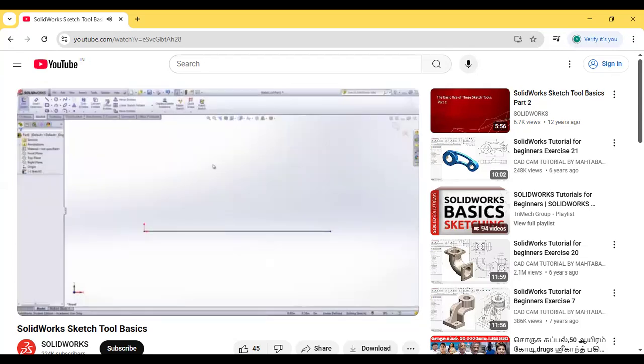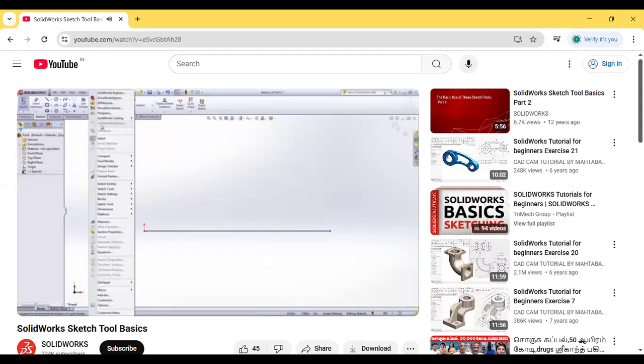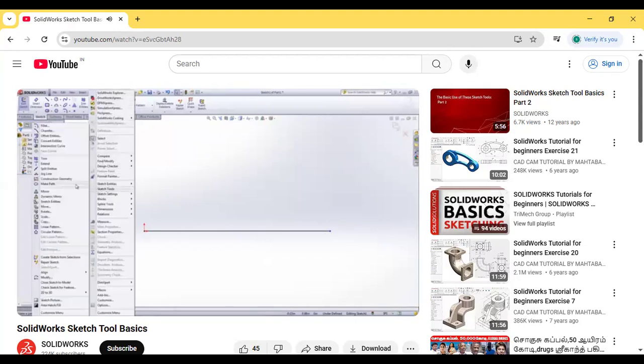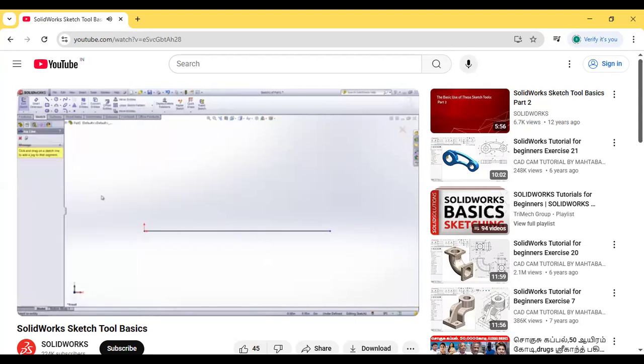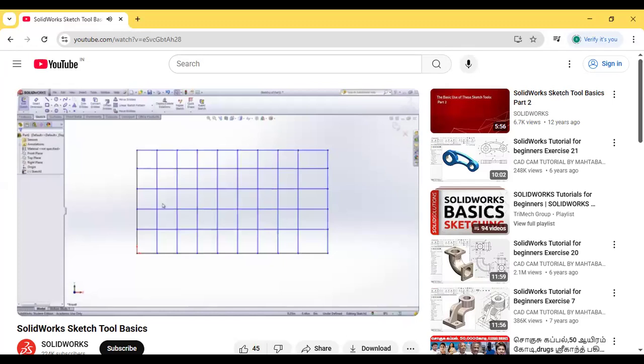The jog line, which can be found under Tools and then Sketch Tools, extends part of the sketch by creating a rectangular tab off an existing line. With this tool selected, click a line and move your cursor away from this point. Now click the mouse to accept the jog line. This tool is helpful to create tabs on a part or to add material around a feature such as a hole.